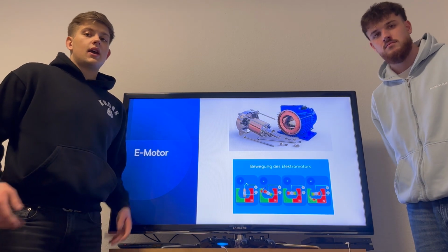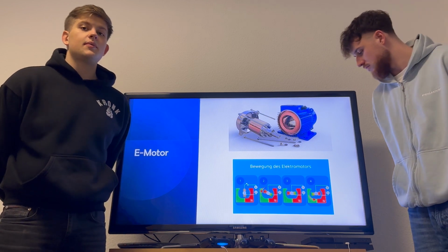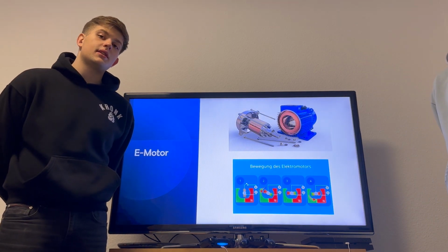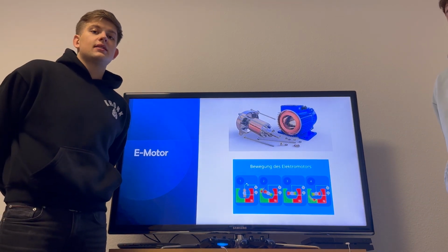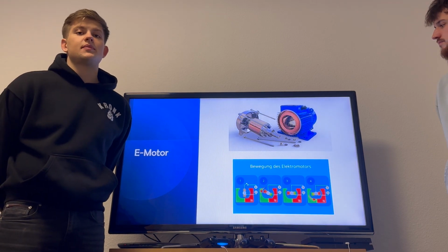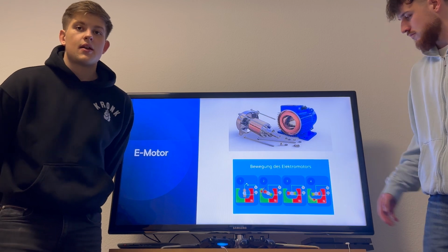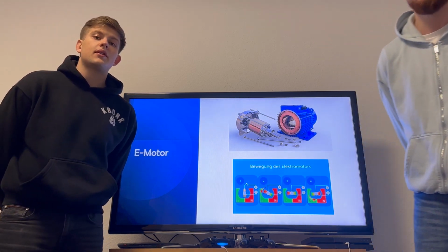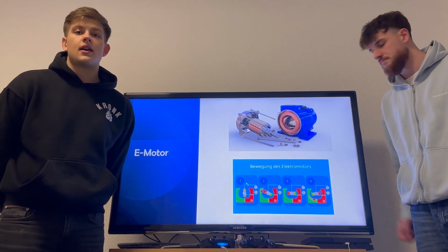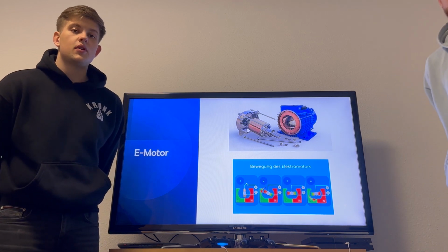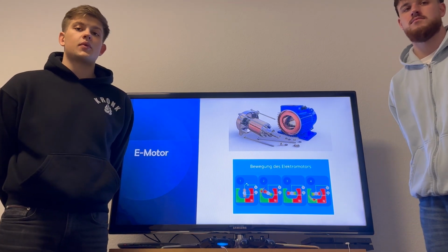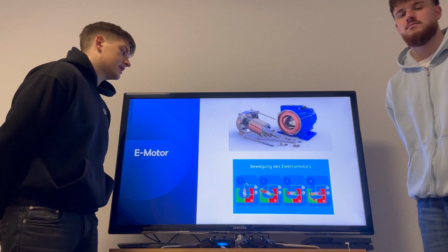The rotor no longer has to rotate at this point to keep the electromagnet continuously rotating. The magnetic polarity of the rotor must be reversed. This task is performed by the commutator, which is connected to the coil and where the voltage source is applied. It switches the north and south pole of the rotor. Afterward, the process repeats from step 3.